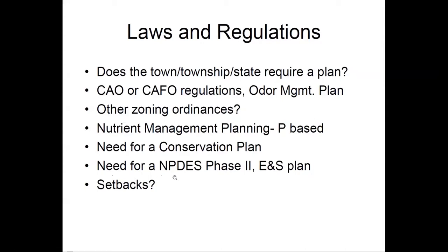Is there a need for a non-point, I forget what that means. That's a water quality permit or an erosion and sediment control plan. If you're doing a lot of construction work, you may need to consider erosion and sediment control. And in Connecticut, a lot of our towns, if you're opening up more than an acre, require an erosion and sediment control plan. Again, are there setbacks that are required by your town, state, or county?